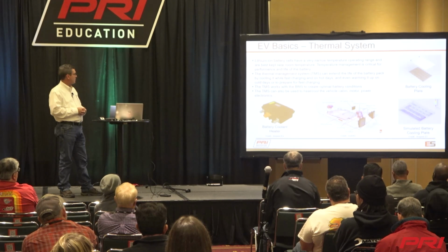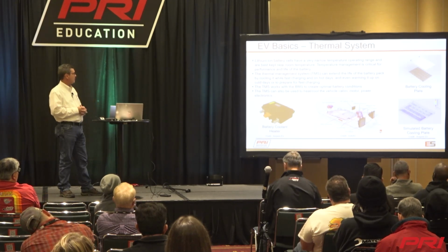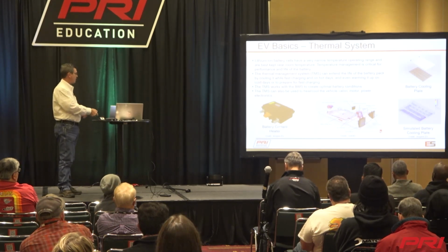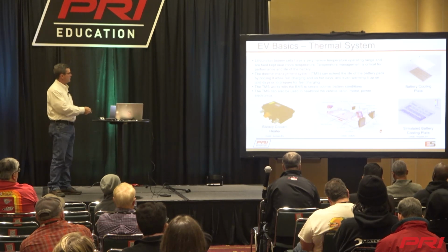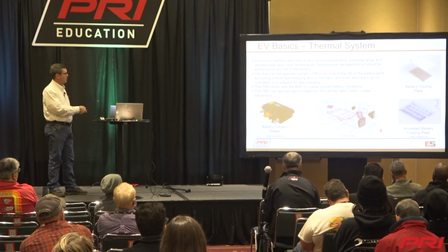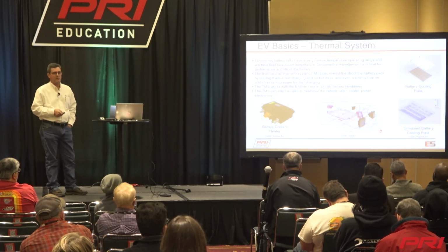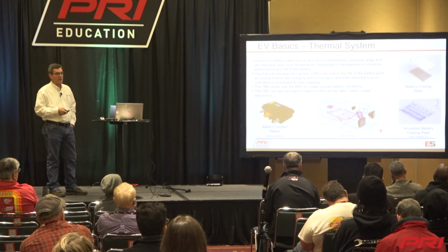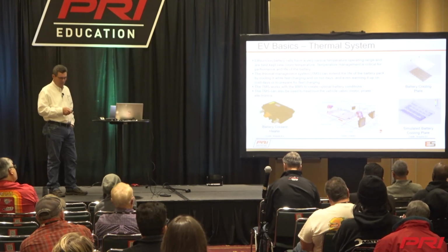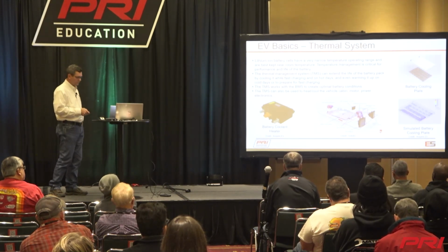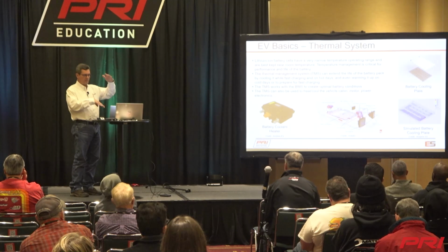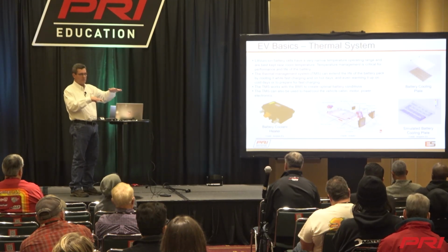And then this TMS can also be used to manage the heating and cooling of the vehicle cabin and the motor and the power electronics. So you see down here, this is an example of a battery coolant heater. These two bottom pictures here in the center and right show the layout of the cooling path through the battery pack. And there's a lot that goes into that. There are ways to model that so you can look at optimizing it and make sure it's going to be adequate through the operating range. These are usually like sandwich plates that are put between the levels of the battery pack, either top and bottom, and if there are multiple levels, they're going to go in between.